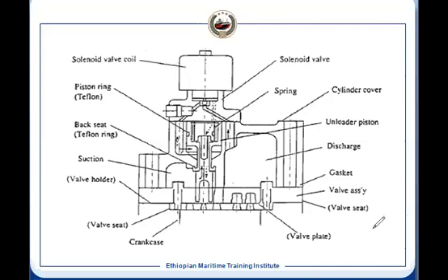Okay, so this unloader is mounted on each cylinder unit, right? Yeah, each cylinder unit on top, on the cylinder cover. Yes, but it's not driven by oil, it looks like. No, it is not driven by the oil. It can be driven by the oil also, but in this case, it is driven by our discharge pressure. This is the discharge. This is connected to it.